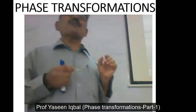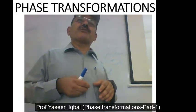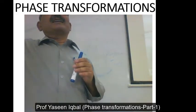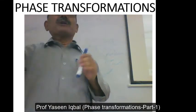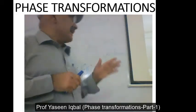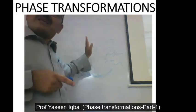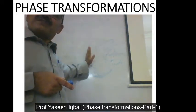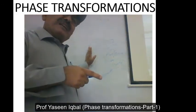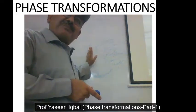DTA is like a person standing in the way on the road, and you ask him where is Peshawar University, and he tells you this. Then you have to go to this direction. It doesn't mean that go to the end of the earth, but you should have a logical thinking that what is the next technique I can use. Then heat the material at different temperatures, at the same temperatures for different time intervals. Carefully, I am telling you very important point. Heat the material at the same temperature for different intervals of time.